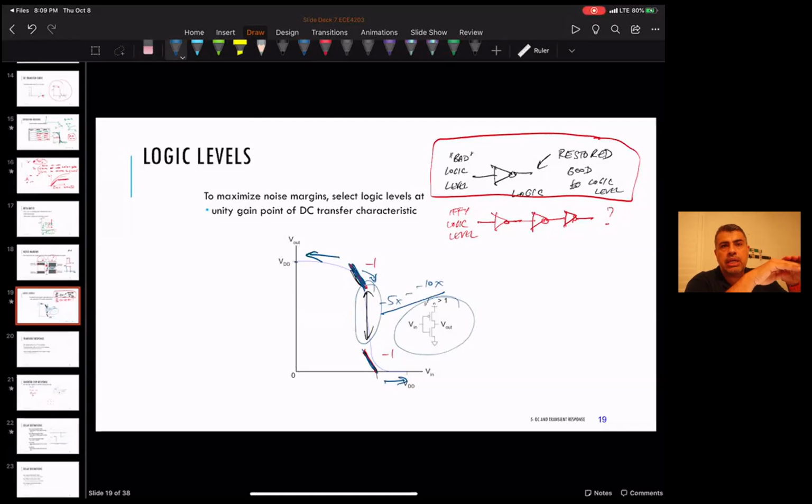They just keep the lengths at minimum in almost every case. Very rarely in logic do you see the length of a transistor higher than minimum. Sometimes you see it, but rarely. So basically you're playing around with the widths, and by adjusting the widths of your N and P-type transistors, you can optimize the noise margin for your gate.